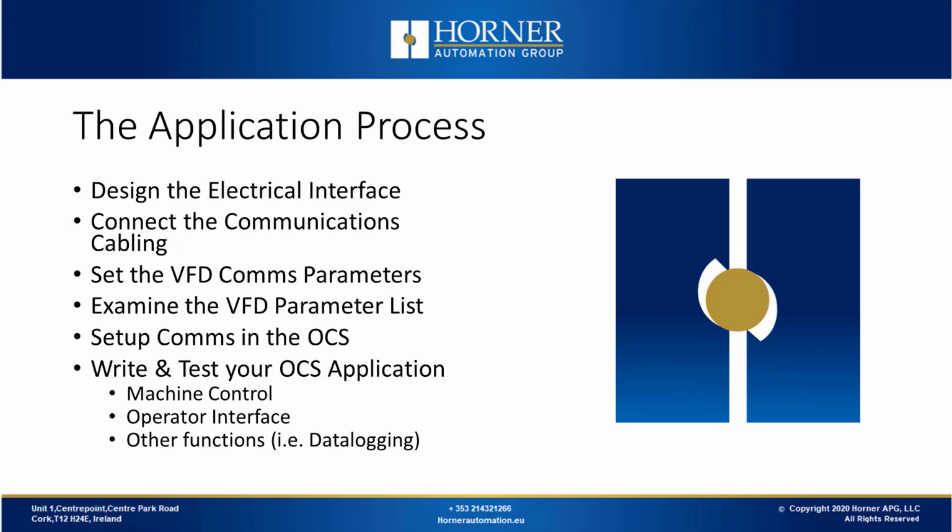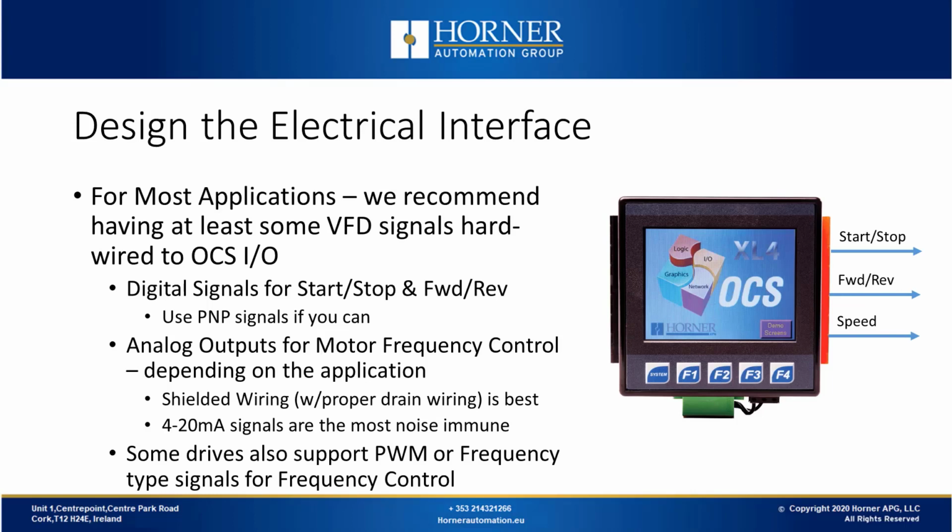Then you'll set up communications on the OCS side of things in Cscape. Lastly, you'll be writing and testing your application from a machine control standpoint, programming any screens that you may want to develop with live data and set point adjustments, etc. If you have any other functions you want to perform, like logging data from the drive, those are also available. Let's start with the electrical interface.